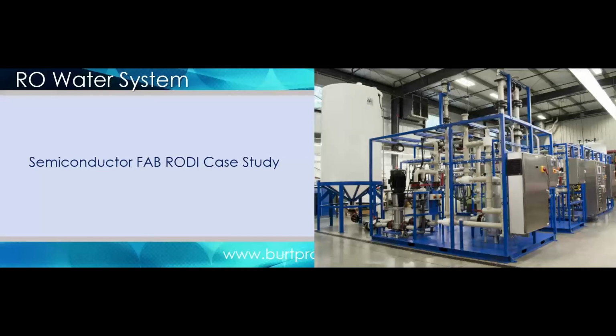If you're a pharmaceutical company, you're sanitizing it every day. Semiconductor, possibly every week or two, or somewhat more continuously when you talk about the electronics grade systems. And then in general, laboratories, places like that, depends again on what the tolerances are of your water quality. Generally, once a quarter to twice a year is a fairly reasonable estimate if you're talking about just an ASTM, say 3, or one of those types.